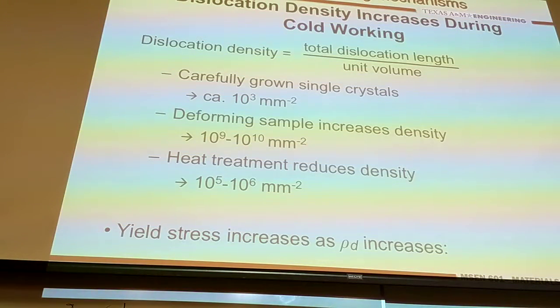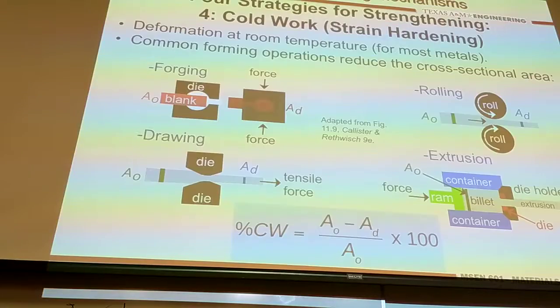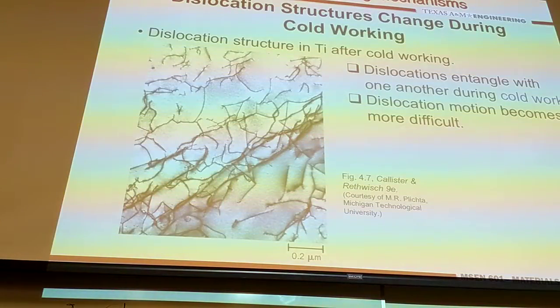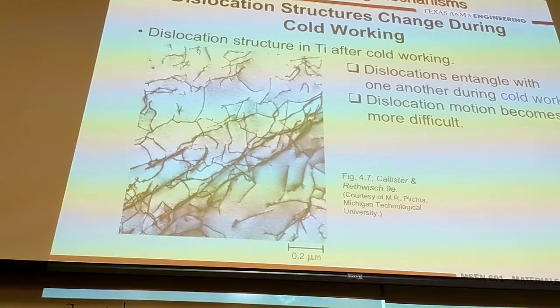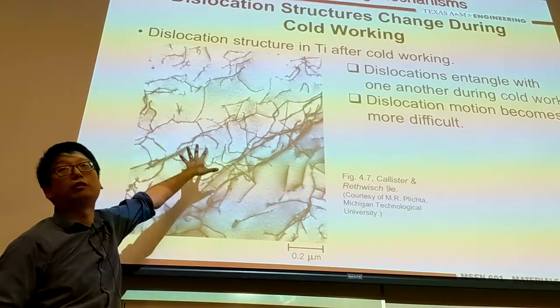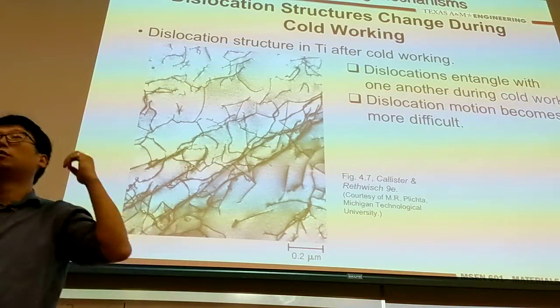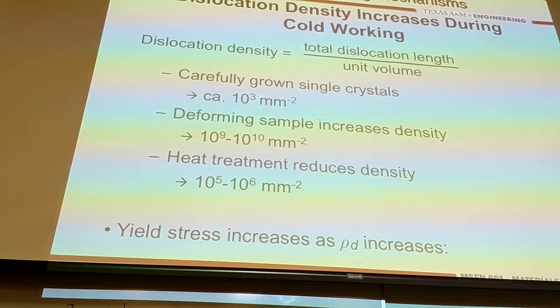So you measure the dislocation lines. Imagine you sum the length of all those lines, for all dislocations inside, and divide by the total volume, for example the volume of this whole chunk of titanium. That corresponds to the dislocation density. So dislocation density has a unit of what? One over area. It's the reciprocal of area, because it is length divided by volume.